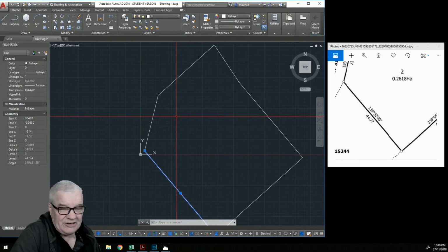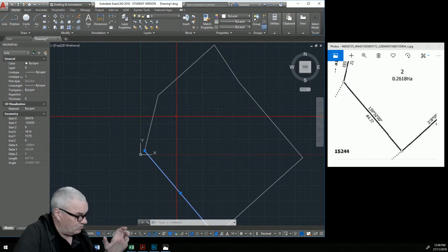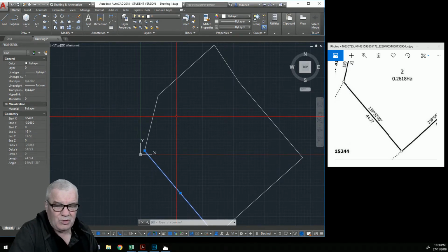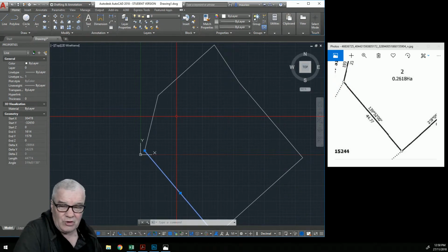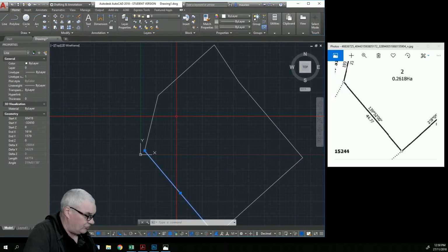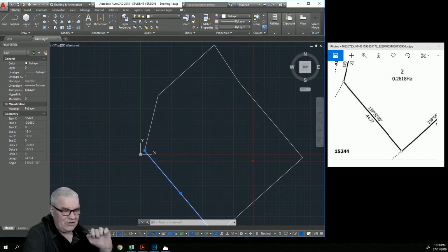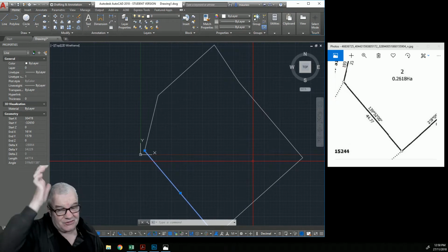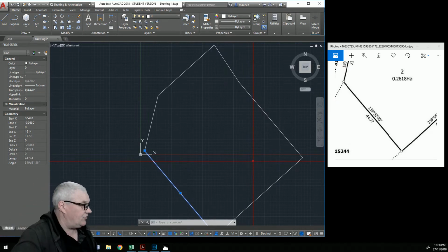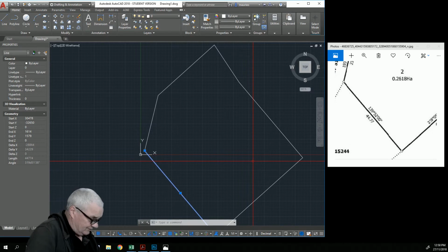So that's why you always leave the positioning of the building open, so that you pinpoint the critical corners, so the building can be positioned according to your resource consent requirements, and let it float out into the areas where it's not so stringent. If this becomes critical, you need to talk to your surveyor and get an adjusted model made that adjusts out the error and distributes it evenly.